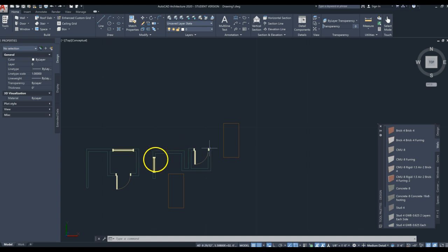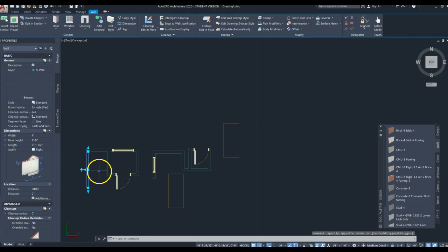As the final thing, I want to go back to the walls for just a minute. If I click on this wall, or you can select it by clicking and drawing a space that captures the wall, you can change the length right here under the Properties palette where it says Length. Maybe it has to be a 22-foot, 5-inch wall. So you type that out and you click Enter on your keyboard, and there's your long wall.